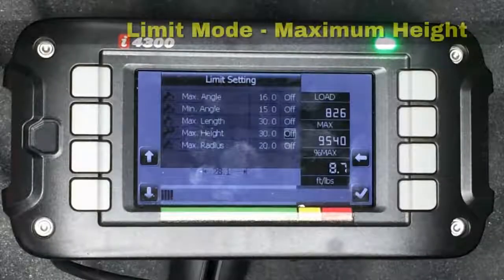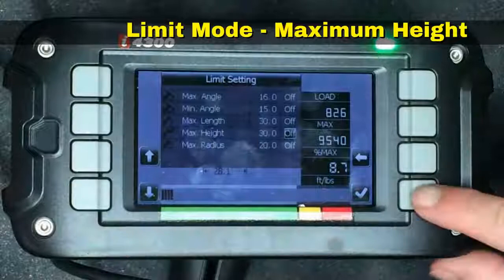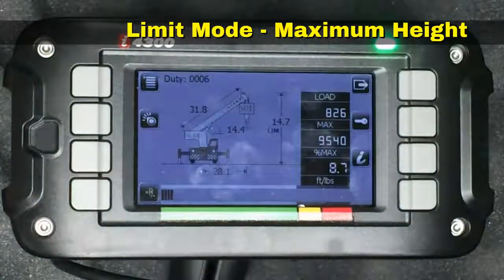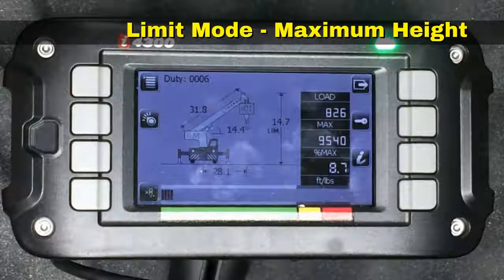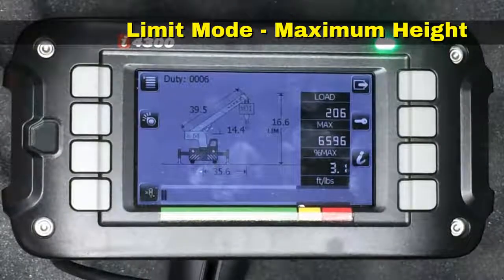We're going to take a look at the maximum height limit. It's currently set for 30 feet, and the option is currently turned off. So we're going to hit the check mark to turn it on. Hit the escape button, and we're going to increase the boom length a little bit. And now we're going to increase the boom angle.